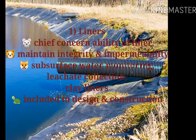Next is the components of leachate collection system. There are many components to a collection system, including pumps, manholes, discharge lines, and liquid level monitors. However, there are four main components which govern the overall efficiency of the system. These four elements are liners, filters, pumps, and sumps.